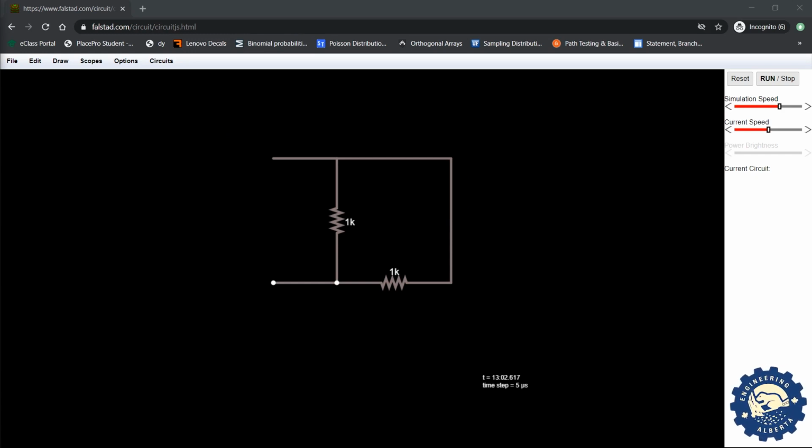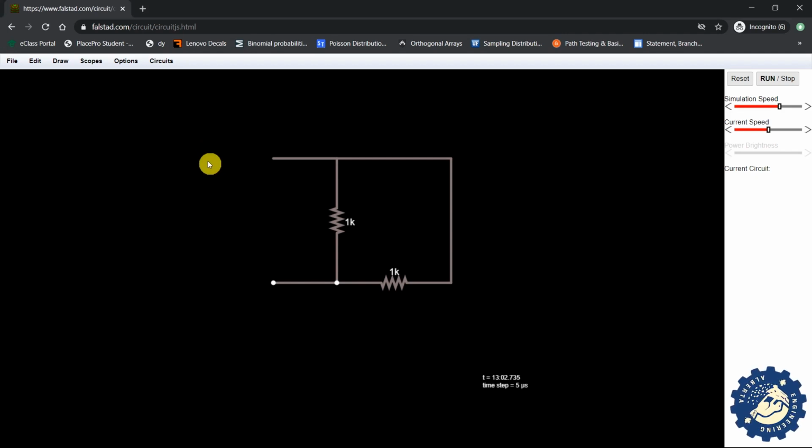One thing to note when drawing a voltage source is that you must ensure that you always draw the input source with the positive terminal above and the negative terminal below. Just like this, I'm going to demonstrate drawing a voltage source on our circuit right here. So I hit V for voltage source, and I click and drag from the bottom up. And that, guys, is how you draw your voltage source properly.